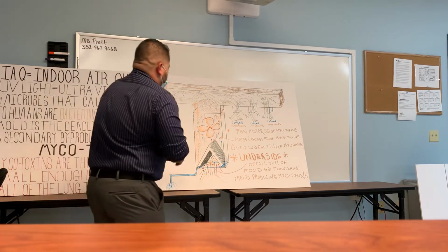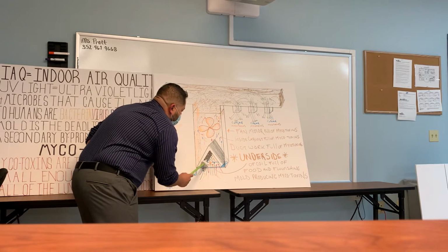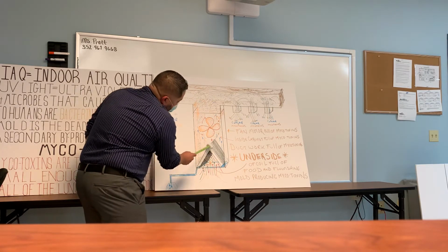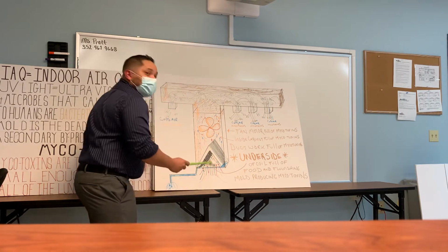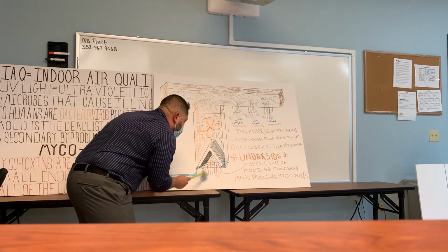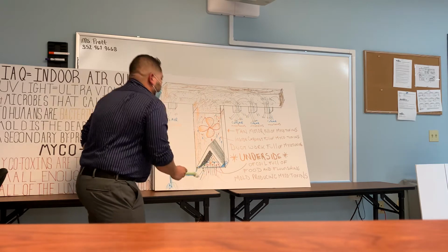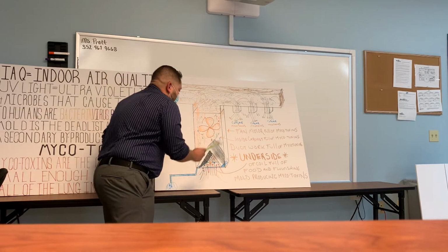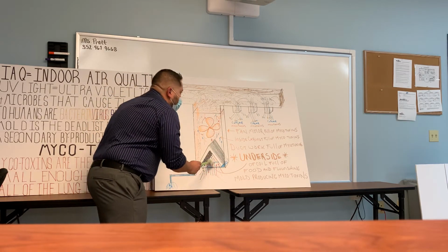So when we look here, we'll see that the bottom side of the coil is where all the food is. The top side is still relatively clean because the coil is about that thick. The food can only get on the bottom because air is being drawn in through the bottom. So that's why the UV light cannot be up here. Must be at the coil, must be underneath.